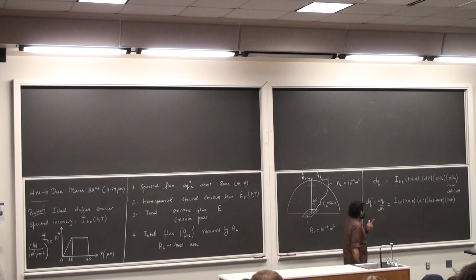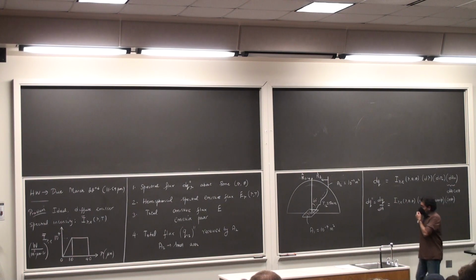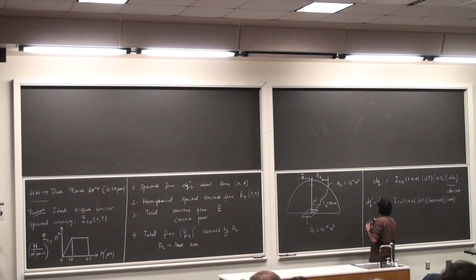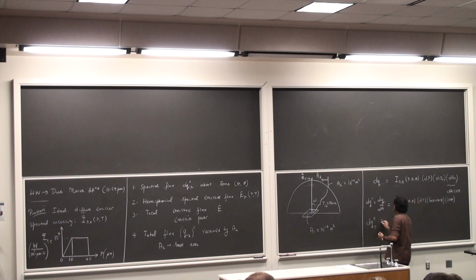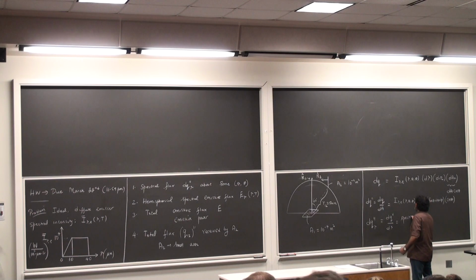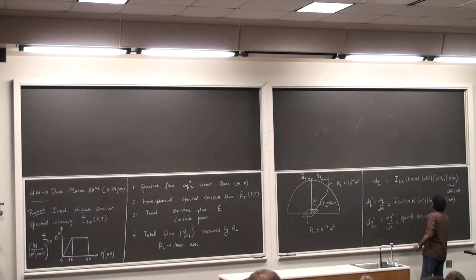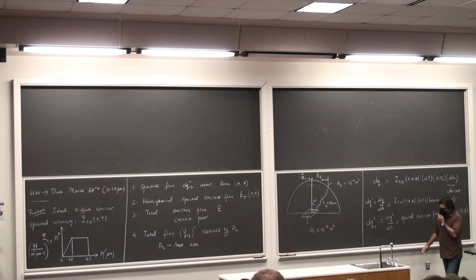Now, I'm going to divide this emissive flux by the fraction d lambda, and here is what I'm going to end up getting. dq double prime lambda, this we are going to define as dq double prime by d lambda. This is the spectral emissive flux about a specified direction. Does this make sense everywhere?